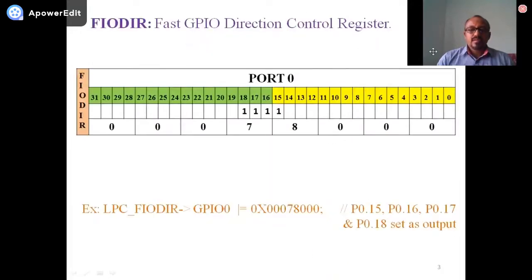To configure the register as a direction, as you know, the microcontroller has to generate the signal to the stepper motor. These pins have to be set as output ports. By default all ports are input ports. We have to set it as an output port. For more details about all the registers and register settings, please watch my introductory video for this lab.